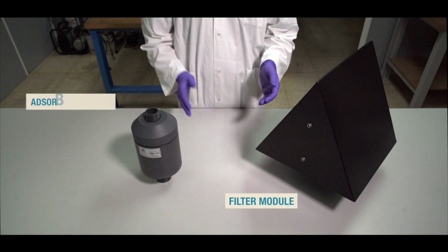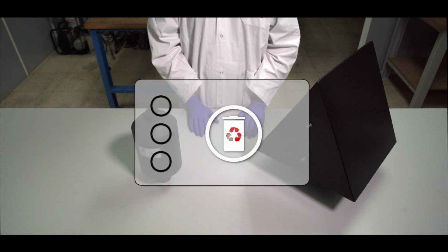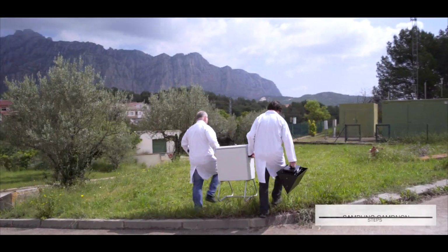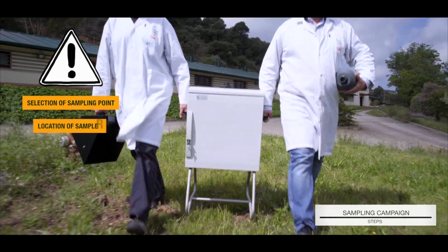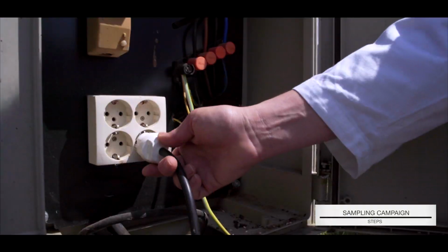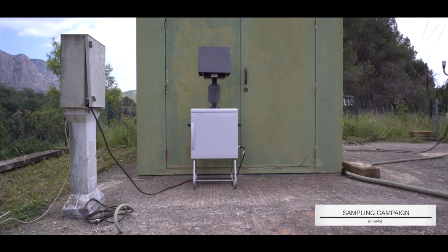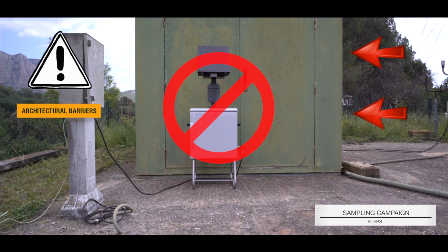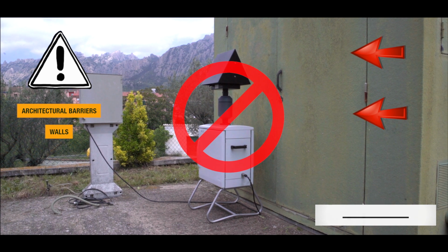Once the modules containing the adsorbents and filter are ready, we are able to start the sampling. In a sampling campaign, selection of the sampling site and the placement of the sampling device become essential aspects to be carefully considered. It is also important to take into account that an electrical power supply point near the sampling site will be needed. Also, special attention must be paid to the presence of architectural barriers, such as walls, which could prevent a proper sampling process.